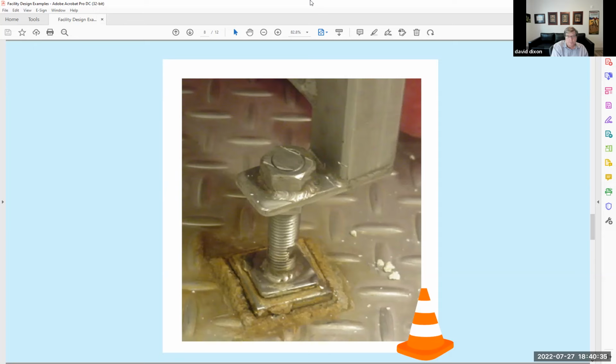Well, break it down, David, because on the other hand, I would otherwise say this is kind of a neat detail where you have this standoff bolt to raise, I don't know, is that the leg of a bench maybe? It's a leg of a piece of equipment, most likely. It's got this standoff, that threaded bolt keeps it up off the floor, but something went wrong at the diamond plate floor, and the corrosion being caused around there suddenly is the problem of the detail. Yeah, there are sanitary legs that should be specified and should be bought and installed.